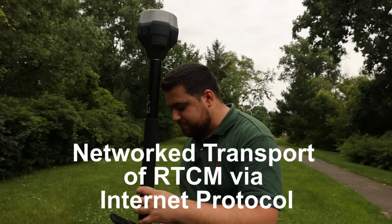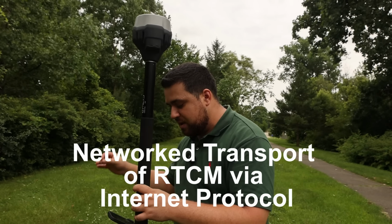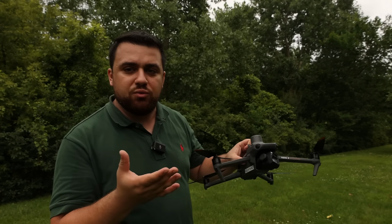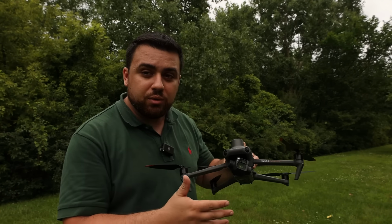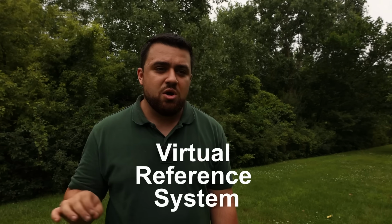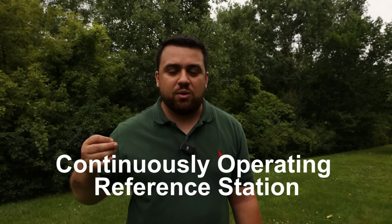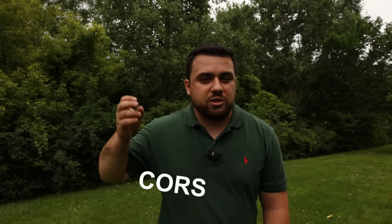Allow me to introduce you to Networked Transport of RTCM via Internet Protocol, or NTRIP. NTRIP is a network solution that will provide any rover you have, including your drone, RTK corrections by connecting to something known as the Virtual Reference System, or VRS, or a continuously operating reference station, or a CORS base station.